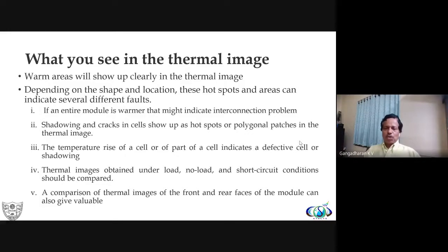Then the thermal images obtained under load, no load and short-circuited conditions should also be compared. This was another issue, because one stretch of readings alone is not enough. We may have to disconnect and see what happens. We have to connect it to the load, get the maximum for that given irradiation, and see. And sometimes we may have to do a short circuiting and see what is happening. So that is also a learning when you start doing this.